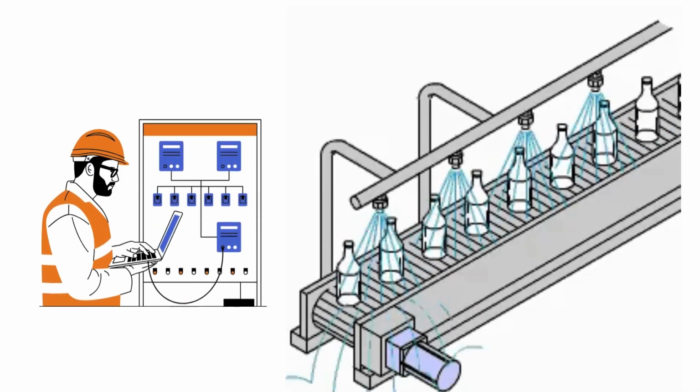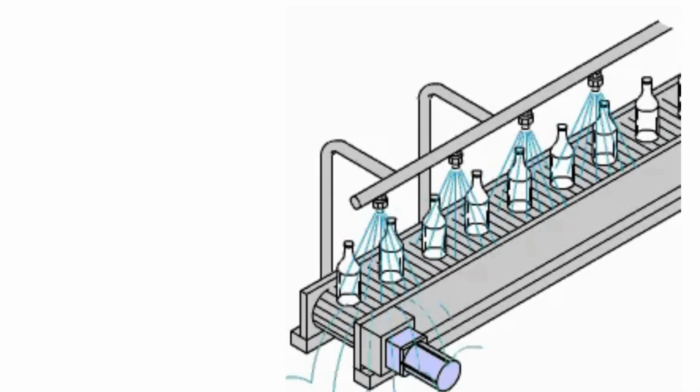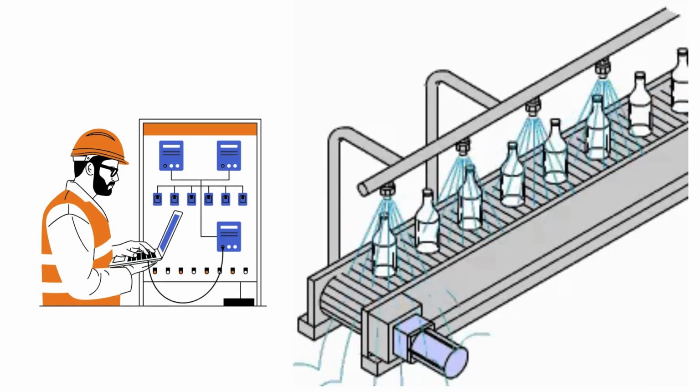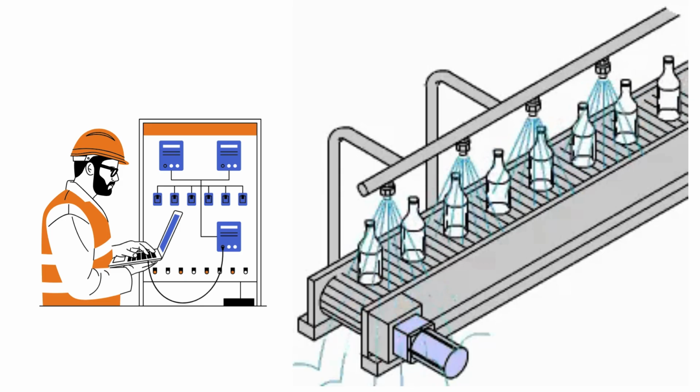Lastly, for routine maintenance, the Sprite QA clean cycle recipe can trigger a cleaning cycle with just 0.1 liters of water and a short filling time of 1000 milliseconds, again with auto mode turned off. This way, each product variation has a tailored recipe, improving consistency, reducing downtime, and making operations far more efficient.